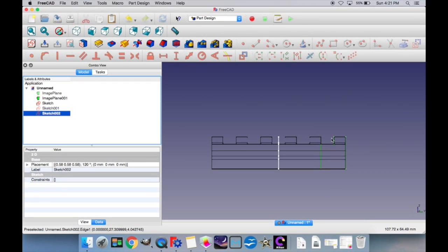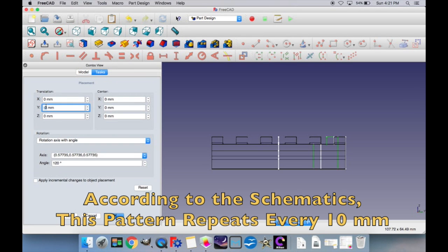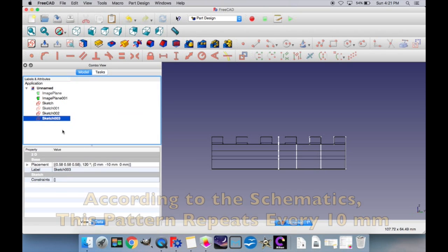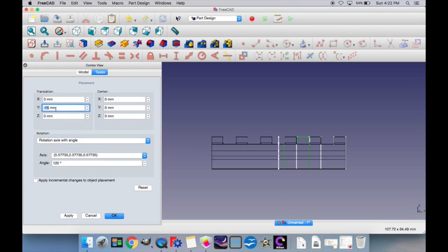Another option you can do for a repeating pattern image like this one is to end the sketch at the end point of the first segment of the pattern, and then copy that and paste it. From the original image we know again how many millimeters this needs to be moved by, and you can continue to do this until you get it into the center here.